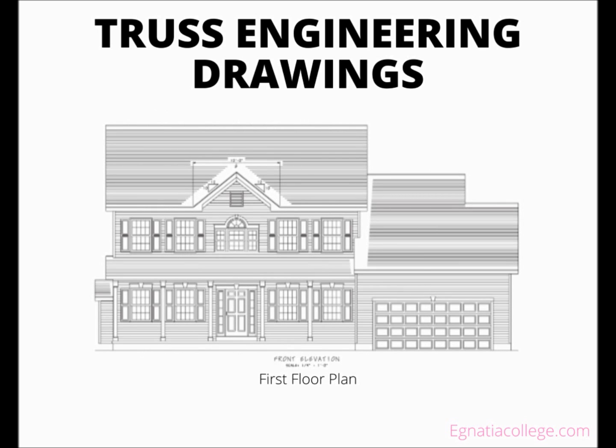Looking at the front building elevations in the figure, you can see that this house has a small gable on the roof above the main entrance. Refer to the truss layout at previous figure to see how this gable is to be framed. There is a triangle with 3 trusses, V2, V1, and T2GE. The main roof trusses T1A run beneath the trusses for the small gable, so the small trusses are applied on the main trusses after the main trusses are secured in place.